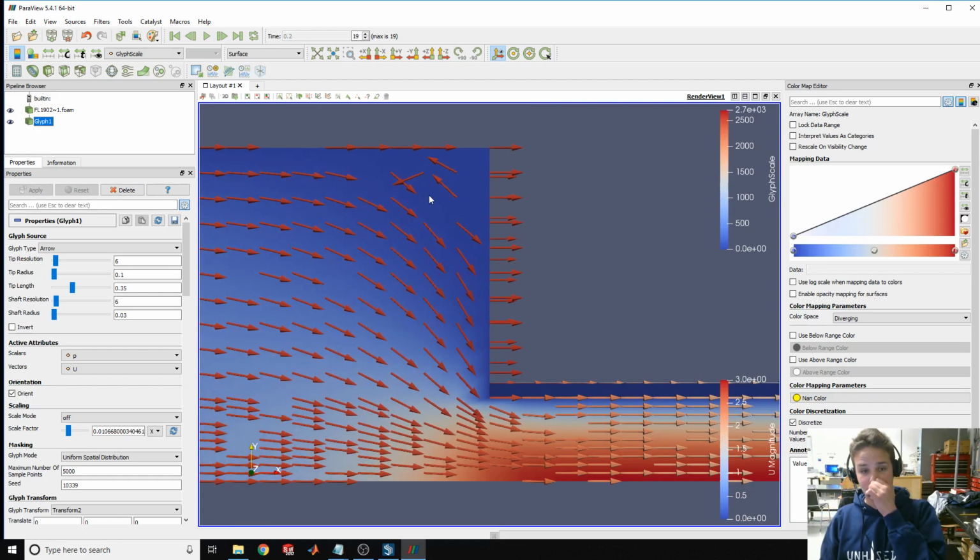Now this is actually kind of interesting. It shows a kind of phenomenon that happens in this corner. You can see that the arrows don't really figure out what they want, and they're going in a weird direction. It's not what you would think it would be. So with high kinematic viscosities, you see kind of a circulation area where it's coming back and forth, and if I ran it for longer, you could see that maybe they keep changing direction.